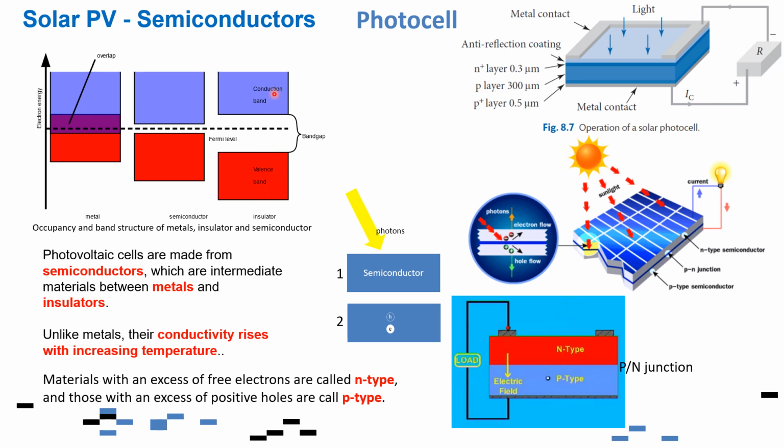On the other hand, insulators have a very large band gap, so there is a much greater energetic difference between the valence band and the conduction band. In this case, the flow of electrons is inhibited. That's why insulators are very poor conductors. They don't allow the flow of electrons. But if you look at the semiconductors, we have a good value of band gap in between. So basically the properties of semiconductors are in between metals, or the conductors, and the insulators.